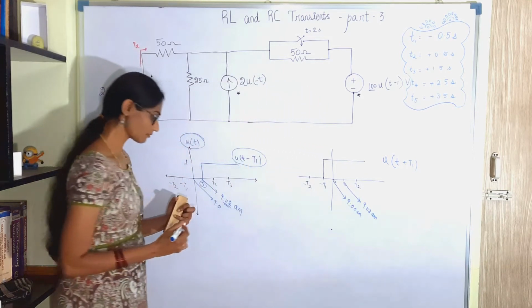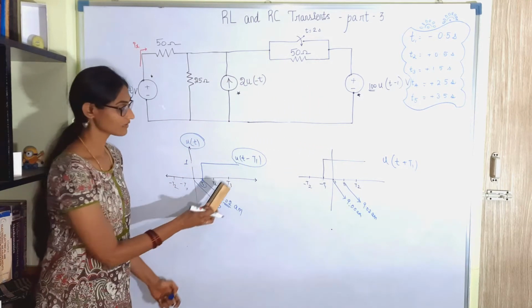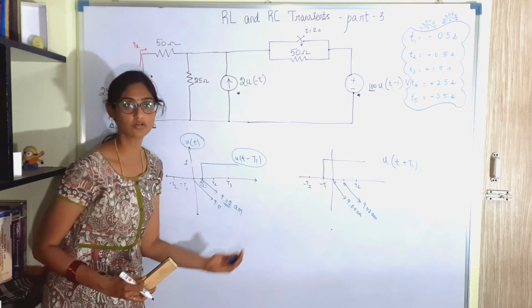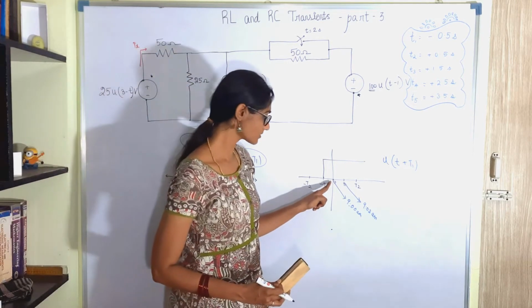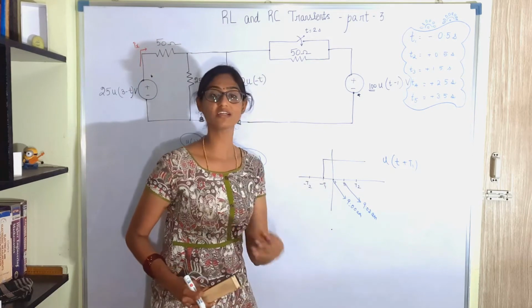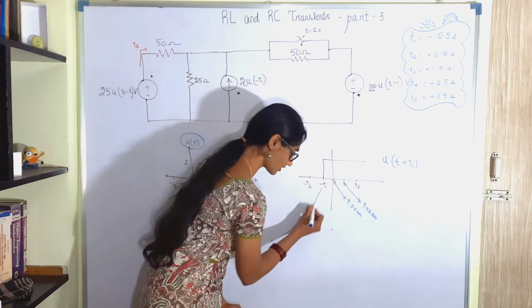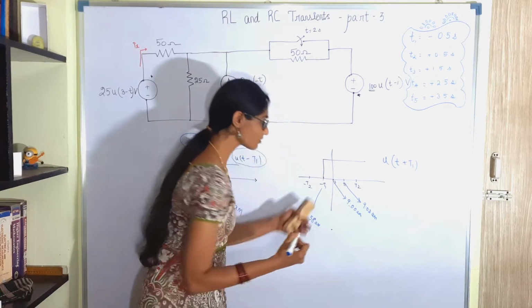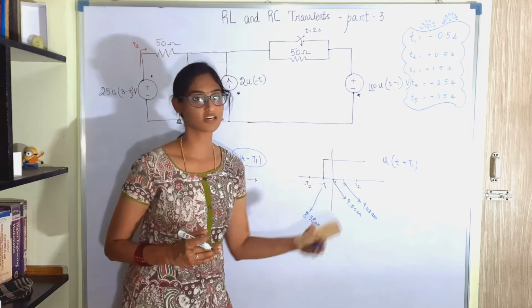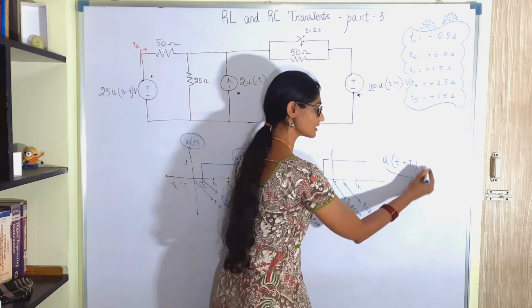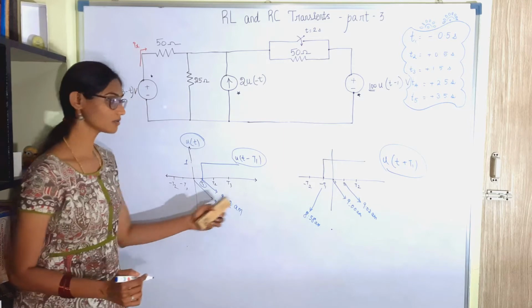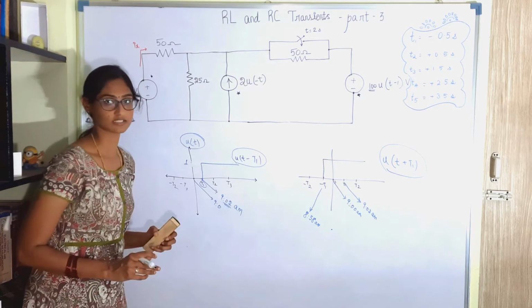If a student comes late by 2 minutes, we can say that the time interval is t minus t1, or it is delayed by 2 minutes. Now, this student is coming at 8:58 itself. Okay, so let us call this time 8:58 am. So this person comes ahead of time. So this signal is u of t plus t1. Okay, so this is how unit step signals are represented.